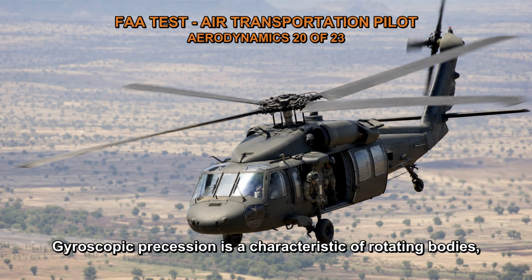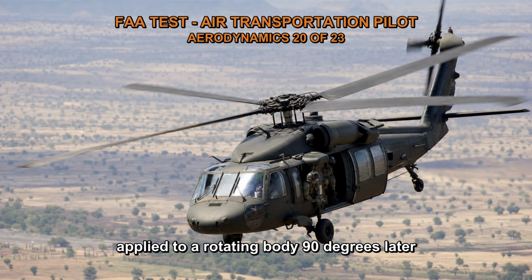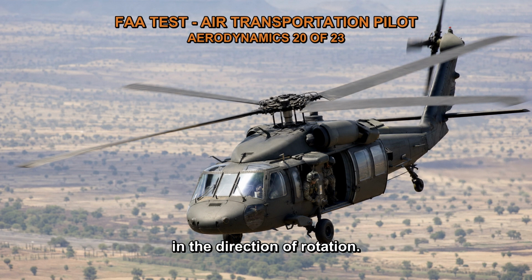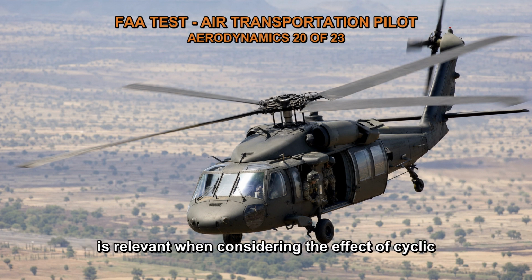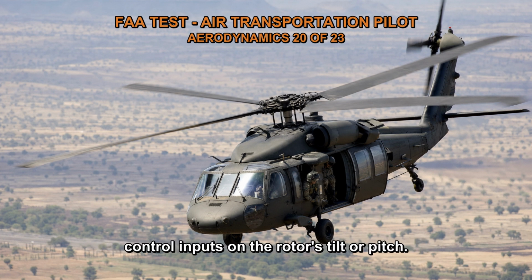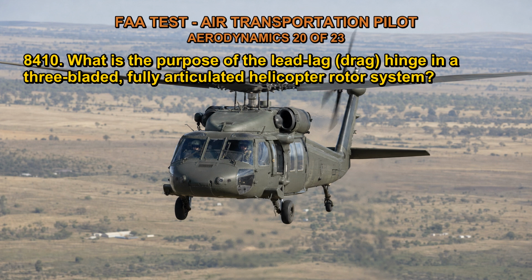Gyroscopic precession is a characteristic of rotating bodies, such as the main rotor of a helicopter. It refers to the deflection of a force applied to a rotating body 90 degrees later in the direction of rotation. In the context of a helicopter, gyroscopic precession is relevant when considering the effect of cyclic control inputs on the rotor's tilt or pitch. Therefore, the correct term for the movement of a helicopter drifting in the direction of tail rotor thrust during a hover is translating tendency.